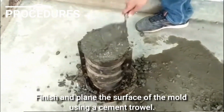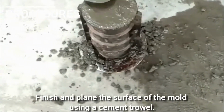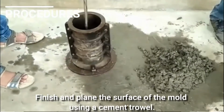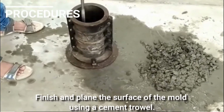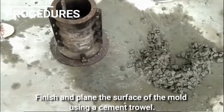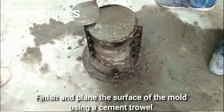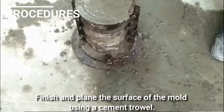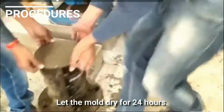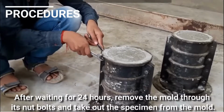Next is using a cement trowel, finish and plane the surface of the mold. Then, let the mold dry for 24 hours. After 24 hours, take out the specimen from the mold.